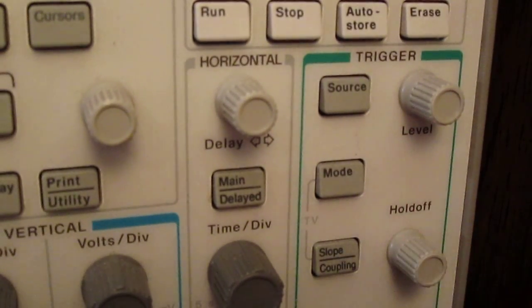Alright, and then another important thing to use is a trigger. So the way that works is you trigger your scope to turn on at a certain voltage. So you saw those spikes that we were getting as soon as we would get that swing in voltage from on to off. Remember when I was measuring like 10 volts? So as soon as I turn on my 555 timer, I could tell the oscilloscope, hey, give me my measurement as soon as the signal that I'm sending to you reaches 5 volts. So as soon as it reaches 5 volts, you give me that signal, and then I can zoom in all the way on that signal, and I can see exactly how high it's going and what kind of spikes we have in there.